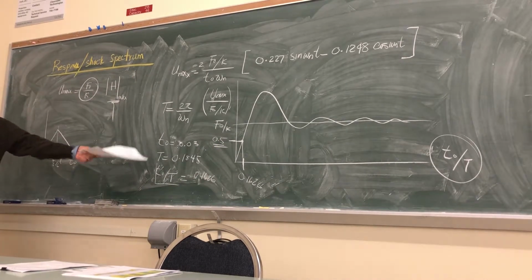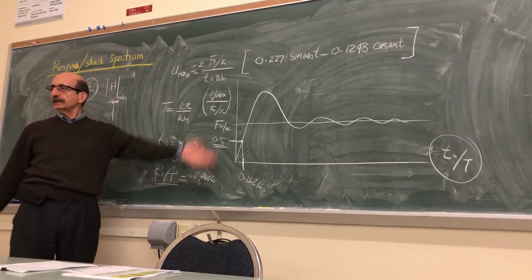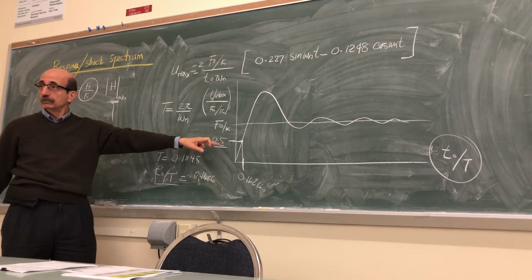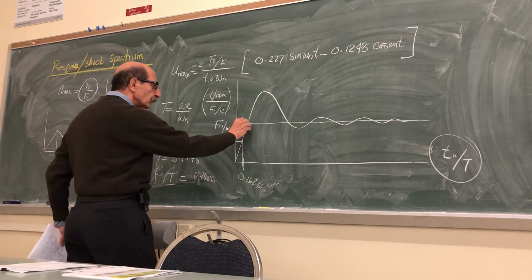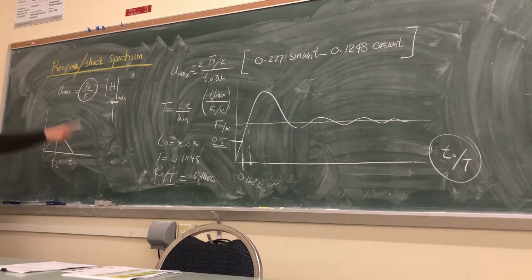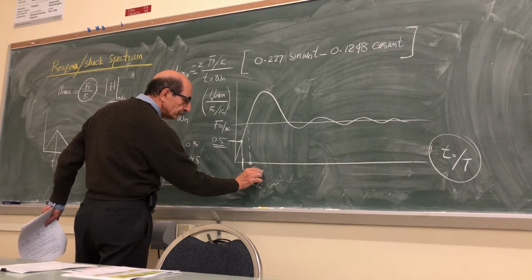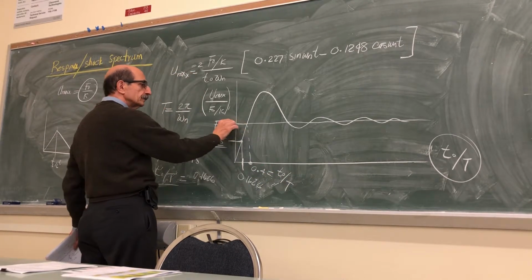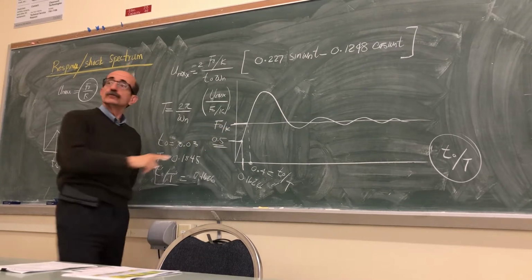So the response spectrum is a plot that can give you quickly the maximum dynamic response. For instance, for this case, these specific values are, if you plot this curve for a loading like this in general, which is what we did, you see that at the value of 0.4 for T0 over T, you will get a response which is equal to the static displacement.